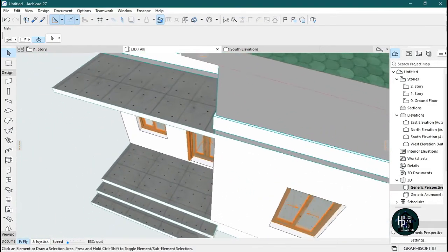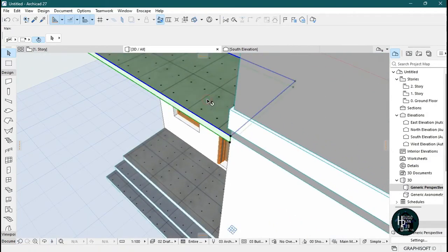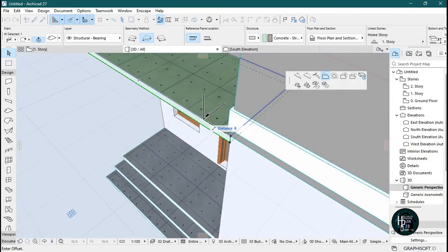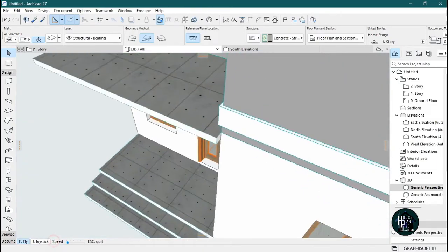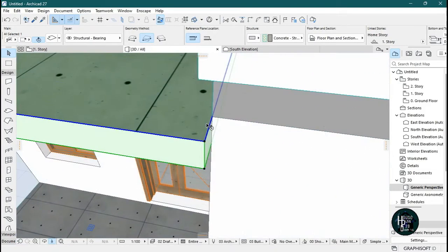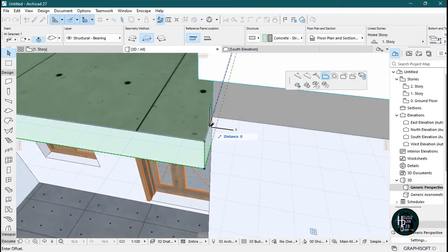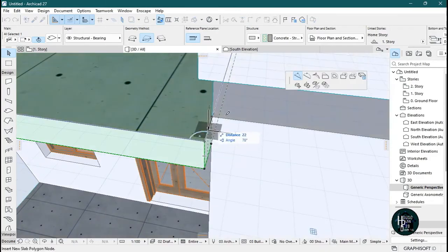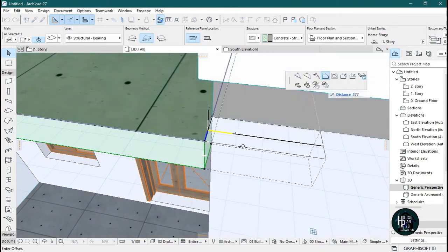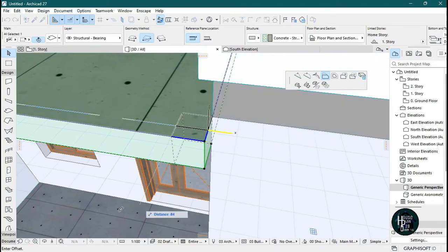So you want to bring this out by 100 again. Click this. Click on this blue line and make sure you're selecting offset edge and stretch it out by 100. Click enter. Okay. Now zoom in very well here. Click the blue line again, click this insert new node and pick this point here. Once you pick that point, click the blue line again, select this offset edge. Okay, so you can offset the edge like this.